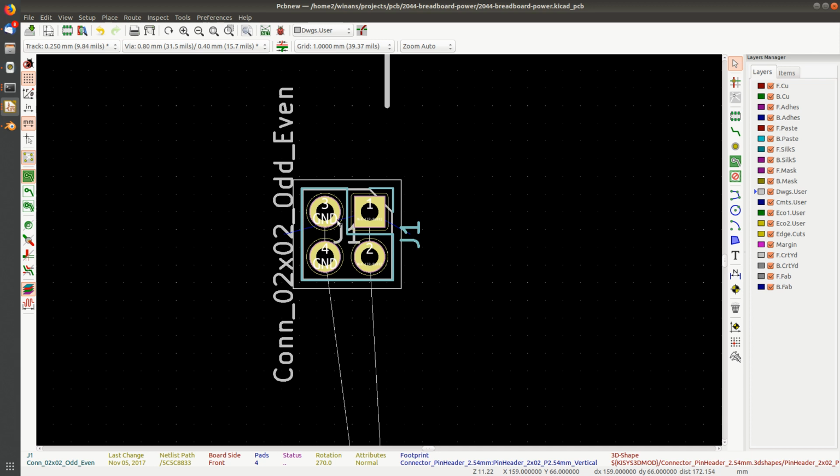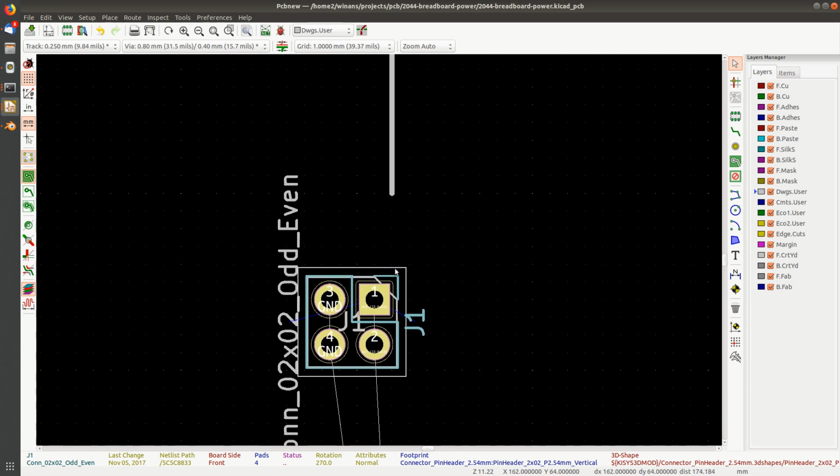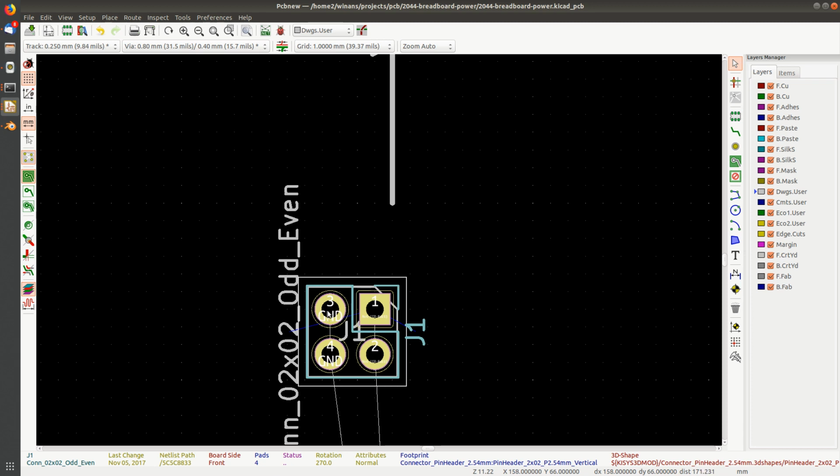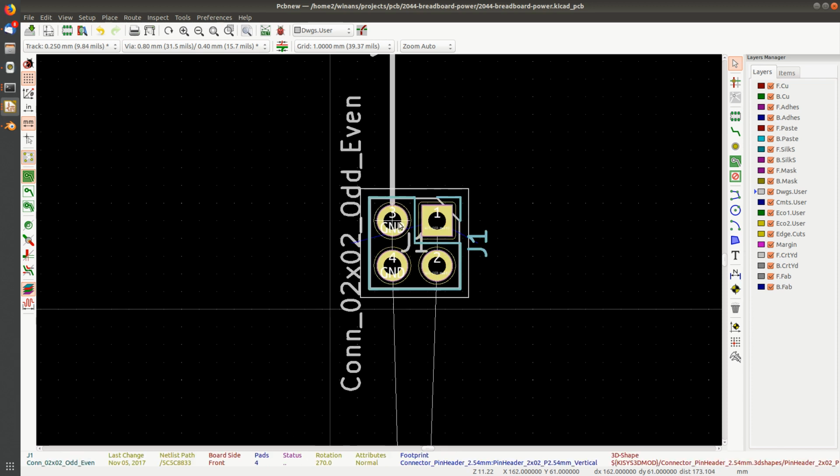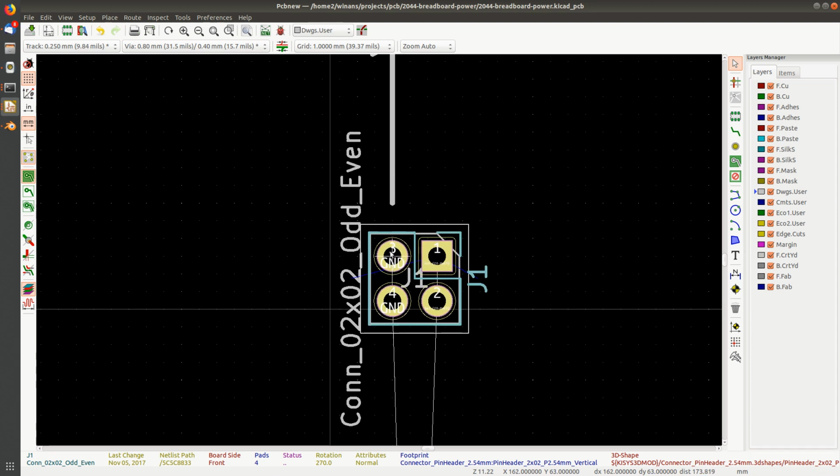But I really want to, let's say, I know this is actually upside down. This is only for the sake of discussion. Let's say I wanted to align it based on pin 3. Sometimes some systems let me move it around centered on 3. Now, this one does. I never noticed that before, so I'm learning something myself while messing with this. If I click this one single pin and I hit M, I'm moving it based on pin 3 snapping to the grid. So that would be one way to get that thing lined up right on there, if this is what I really wanted.